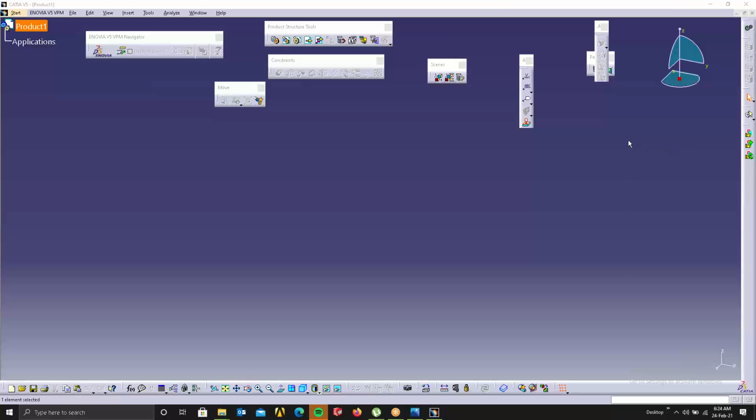For example, straightness, flatness, circularity, runout and everything. It's very critical, because there is no way to communicate with them apart from telling them by word of mouth, like, I need this flatness here. Every time that won't work. So if you store the details in your file, after 5 years the person will take the same component and manufacture it from the file. In the initial stage they knew they needed this flatness, this total runout and everything, but if it's not mentioned in the file, after 5 years they won't know if that is a requirement.